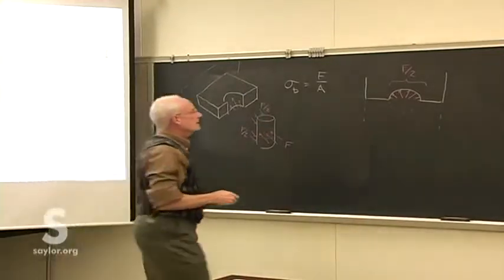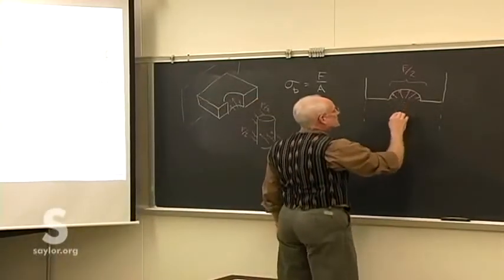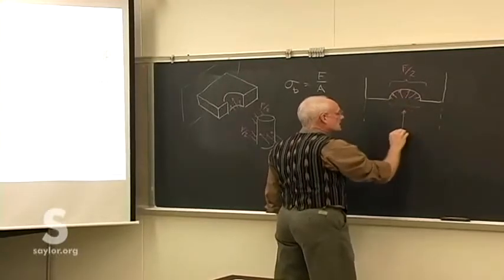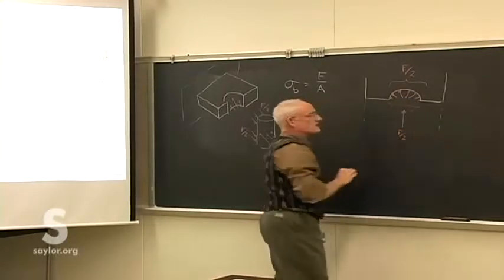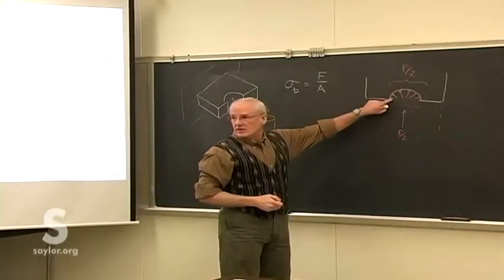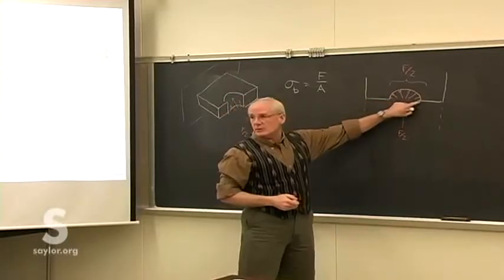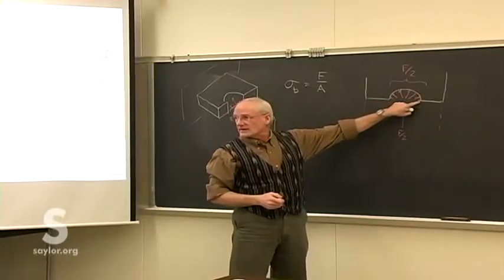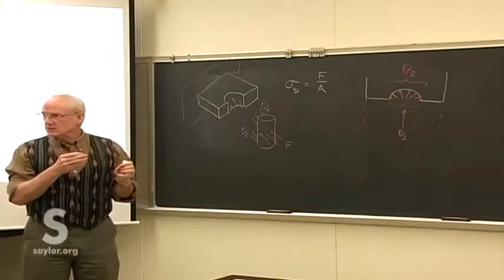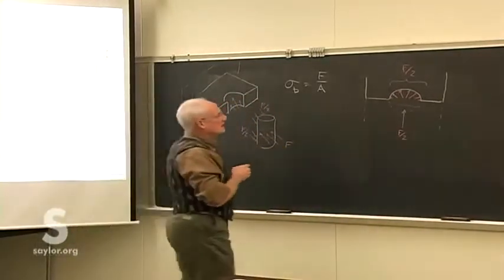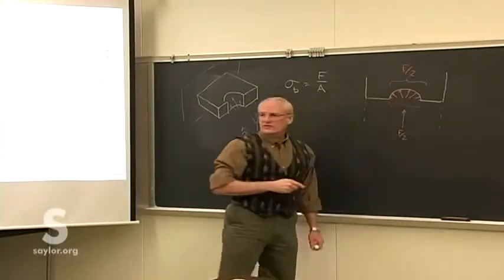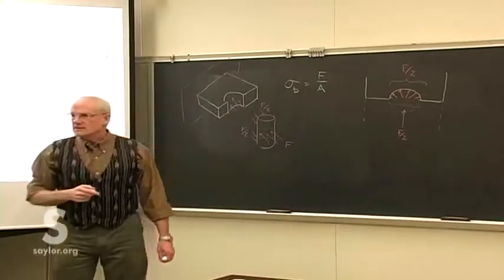It's still a resultant force in just that direction because the little side components on the left have an equal and opposite side component on the right that cancels each other. So all the sideways components have equal and opposite components on the other side. So it gives us a net of this F over 2 straight on.